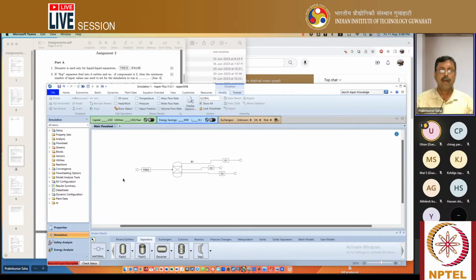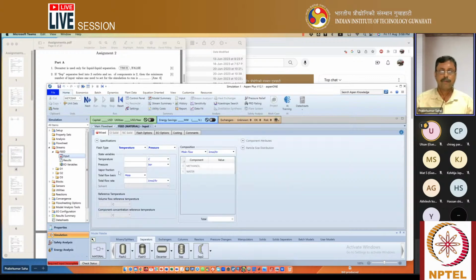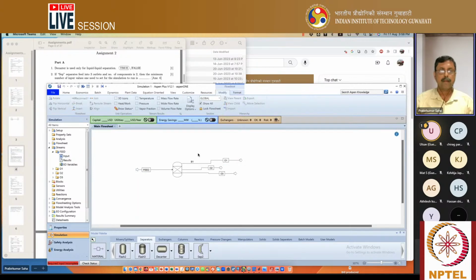Okay. Now we have to fix the feed. So methanol water system, say 25 degrees centigrade, 1 bar pressure, and mass flow rate, say 100. Okay. So press next.